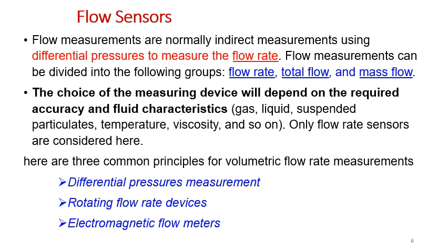Now we will start thinking of the measurement, where we are going to talk about the flow measurement. In the measurement of a flow, we are not measuring the flow directly. The flow is to be measured in an indirect way. Like what? Like measuring the pressure, which can be compared with the flow rate. So we can calculate even the differential pressure, which will tell us about the flow rate.